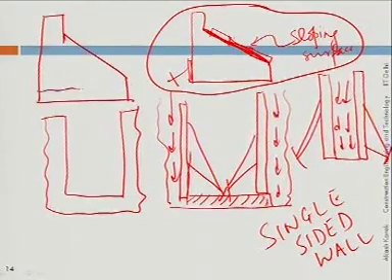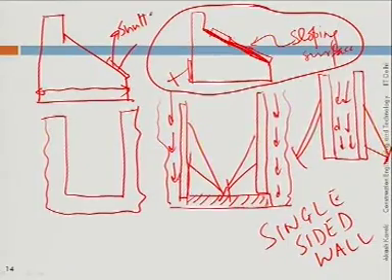So this depth would be very large. So what is done is, normally you cast this wall portion by having shutter only on one side. So this side only you have the shutter or the formwork. So this is how the arrangement is when you have a single side wall, inclined, or rather sloping, having sloping surfaces.